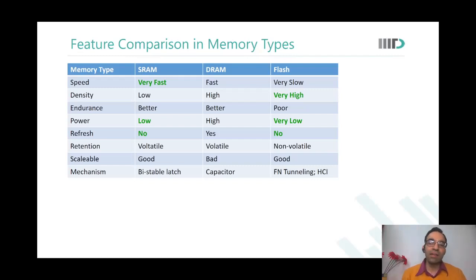Now, let us say the devices are leaking exactly the same way as the earlier technology. In fact, device leakage increases as you scale, but let us say it is the same as the earlier technology. Now what happens? We will not be able to read, it will leak more. So I will need to refresh faster. Okay. Okay, sir. Yes, sir.